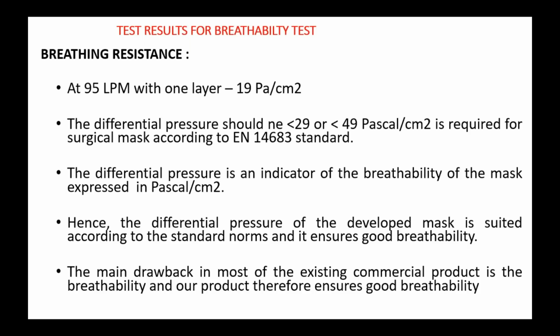And the second test is breathability. That is what we assessed for breathing resistance. At 95 LPM with one layer, the breathing resistance value arrived at 19 Pascal per centimeter square. The breathing resistance will be assessed using the differential pressure. The differential pressure range as per norms should be less than 29 or less than 49.